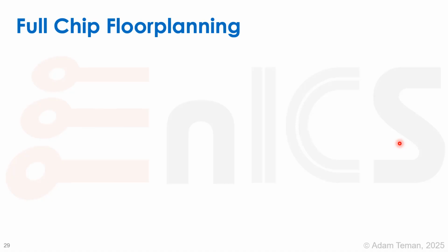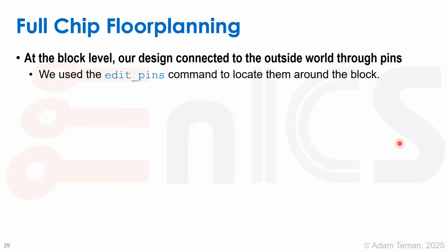So let's discuss a bit about full chip floor planning. At the block level, our design connected to the outside world through pins. We used the edit pins command to locate them around the block. There were many options. We had kind of a complex form or a really long type of command where we could scatter our pins or place them manually one by one around the block.